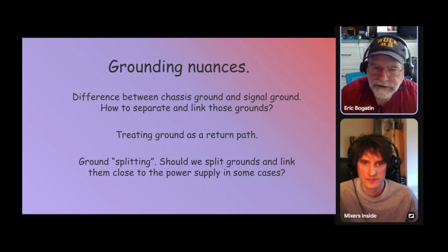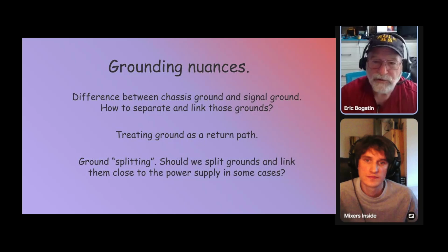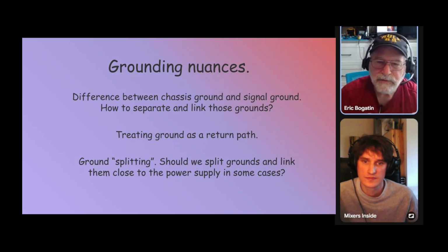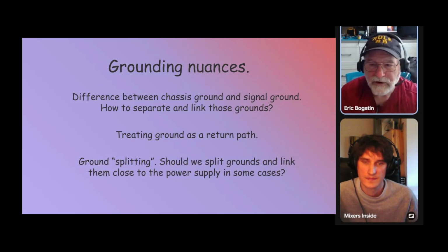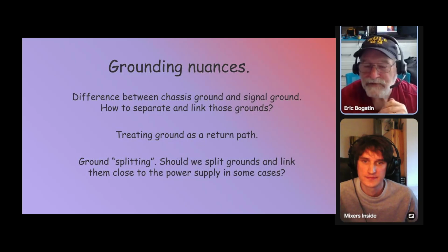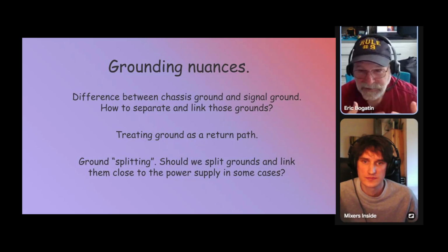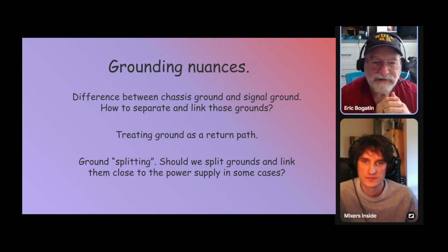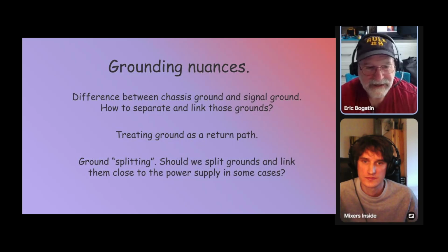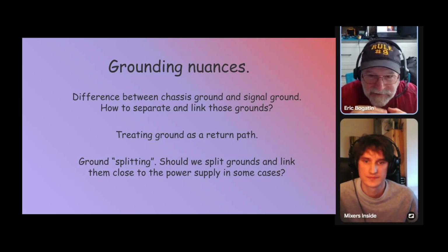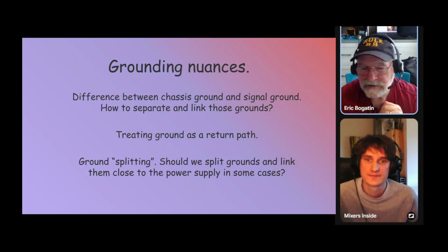But in that 100 kilohertz and below frequency, your important audio range, the return currents spread out, and that gives us resistive noise between the signal lines. Even though they're far apart, we still have current flowing under the signal lines. It's hard to measure because it's really small, but if you're dealing with millivolt signals, even a couple hundred microvolts of noise is going to degrade your signal to noise ratio. So even though it's really small, for your applications, it can be important.